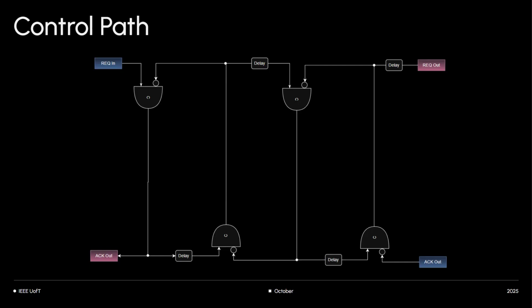In a synchronous circuit, you have one oscillator, a common clock for all of them. Over here, the black magic that you're actually doing, I didn't reveal it but you revealed it, is that you're taking these so-called clock signals and localizing them to each stage, not a global clock. So for example, in a continuous operation of this pipeline, these request and acknowledge signals just look like a phase-shifted clock signal. You get what I'm saying?